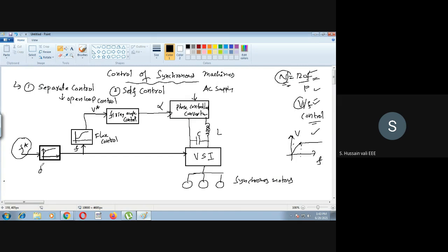Then this is the delay circuit. This circuit will delay your action. The action is that you set some 60 Hz, or some 30 Hz. Once you set it here, the delay circuit is there. Otherwise, the response would be just a sudden jump. We don't want that kind of action. We want a delay so that transients will not occur. So the delay circuit will come here.